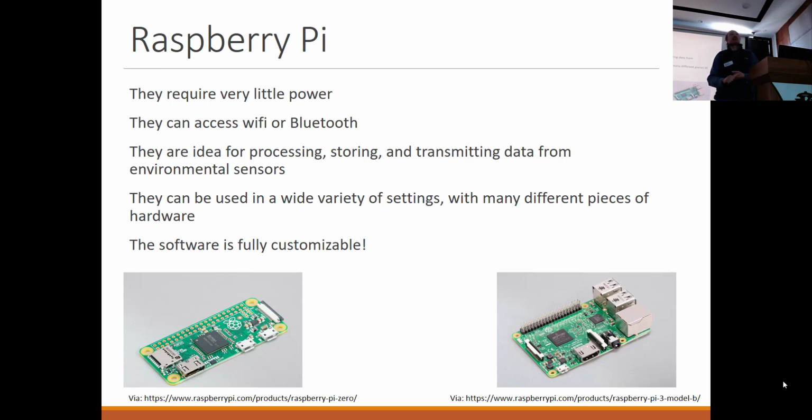So when Bodo and I are installing sensors, generally we have an Arduino or some other kind of small hardware that connects via USB cable, and we have 3 or 4 sensors that all send their data here, and the Raspberry Pi is responsible for taking all that data, putting it into one file, and uploading it through Wi-Fi or through a SIM card to us. So this is sort of like the master computer that takes all the data from different places.